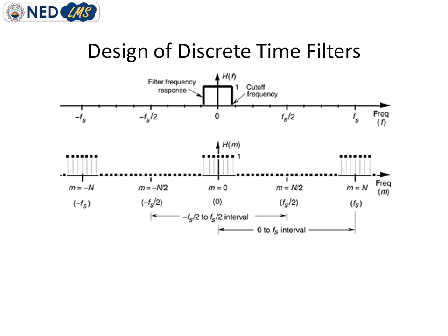So to obtain the FIR filter coefficients, we need to define this periodic frequency response over a single period, which is obviously Fs, as this spectrum is repeating itself after Fs.